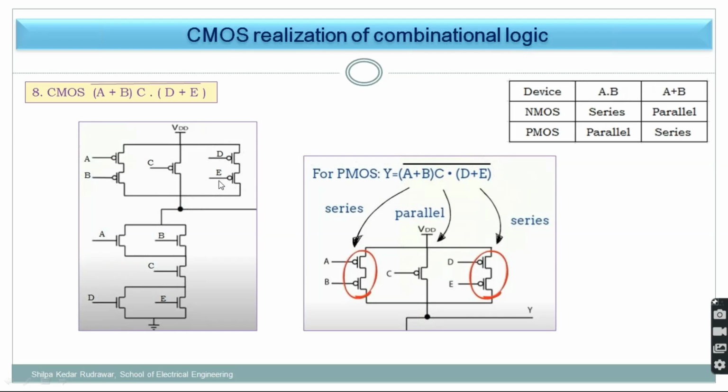You need to remember where to draw the PMOS and NMOS, the pull up and pull down. This thing you need to draw. And last but not the least, you need to remember the symbol. If you are not drawing the bubble, it means you know, but because of a hurry you did not draw that bubble, then it is a totally wrong concept. So again, the opposite of this we need to implement over here.